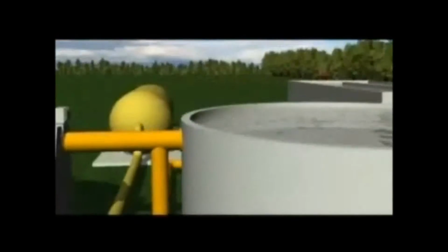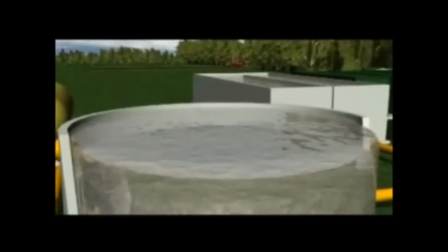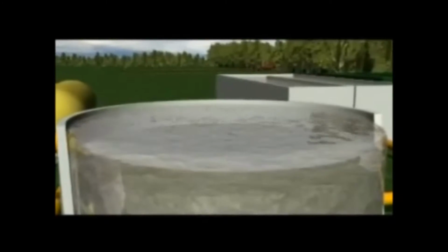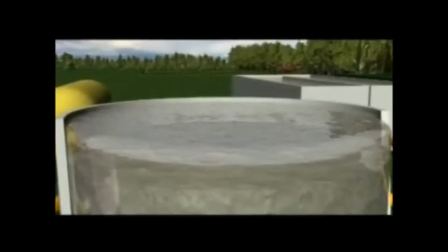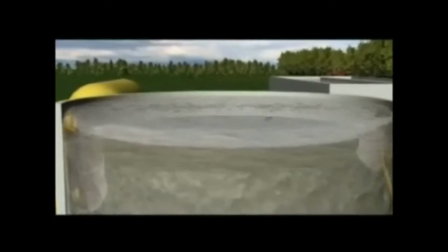Here we use bacteria to clean up the liquid sewage. The bacteria help purify the liquid by actively feeding on it and turning most of it into carbon dioxide, water and nitrogen. In biological filters, we encourage bacteria to grow in deep beds of irregularly shaped stones. Gaps between the stones circulate air, which lets the bacteria breathe and thrive as the liquid passes through them.